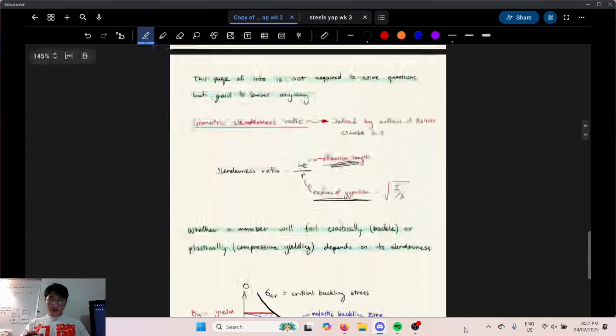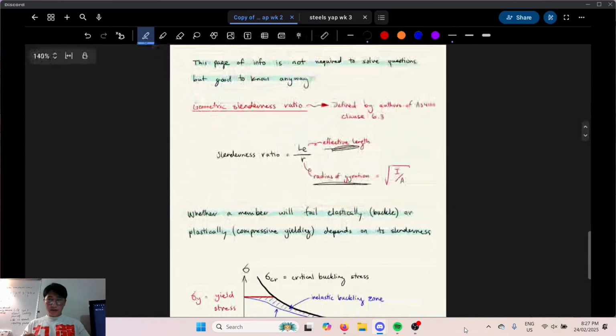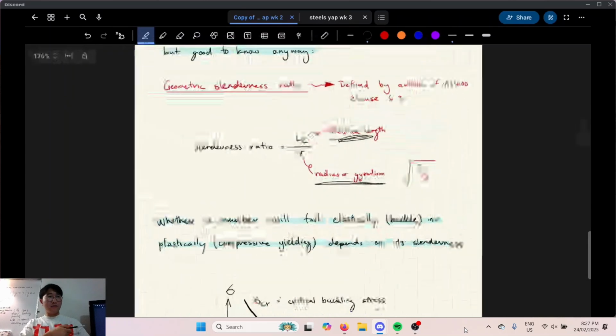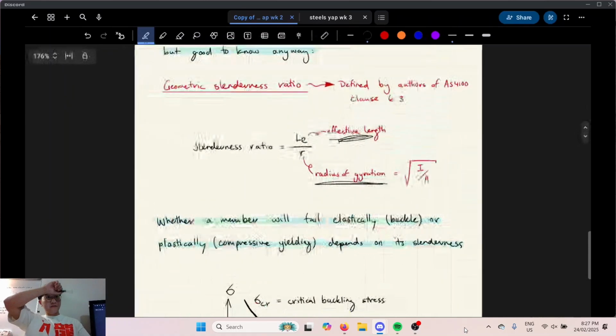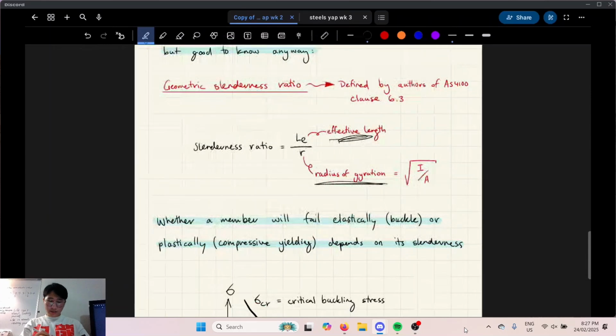We'll talk about radius of gyration later, but it's something you've probably seen in solid mechanics before. It's the square root of I over the area. So you can actually have two versions, Rx and Ry, because it depends on the axis, the major axis, minor axis, all that. All you do is change whether it's Ix or Iy. But the cross-sectional area is not directional, so that will always stay the same. Any questions? No, sir.